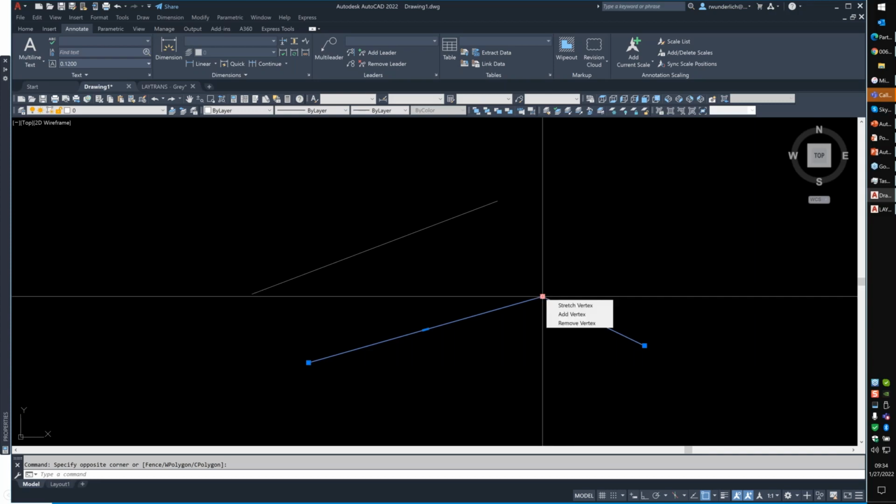So anytime you have a dialog that pops up on a grip, that's a multifunction grip, so you can do more. Let's see, do you recommend storing blocks in the template or in a tool palette or block palette via library? That is going to depend, Brock, on how many blocks we're talking about and if they're common for everyone. I generally don't put blocks into a drawing and then erase them, because if someone goes in and purges before they've done anything, they remove all those. I'm usually a big fan of having them either in a tool palette or using block palette. That's typically what I recommend.